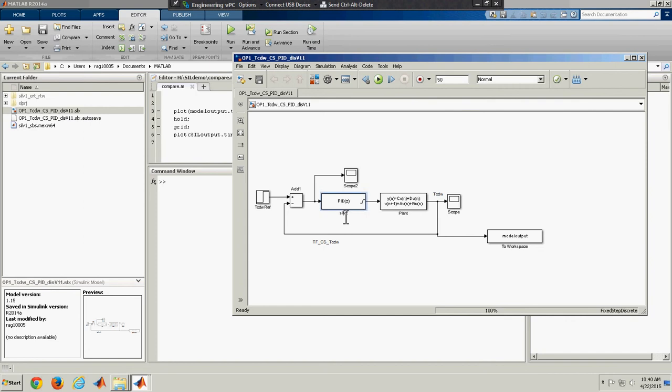So make sure they are not overwriting some previously generated files or controllers for some other Simulink models. If you can make sure of that, then we are ready for the configuration settings to prepare the system for autocode generation.